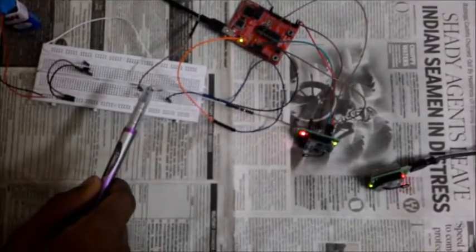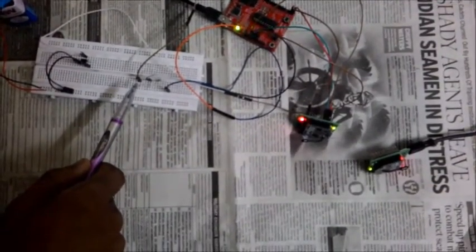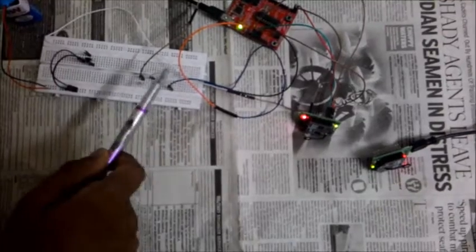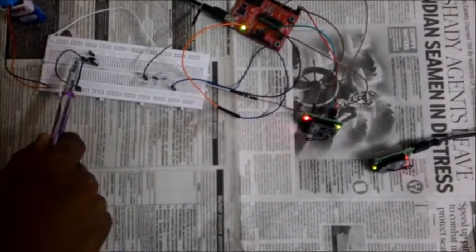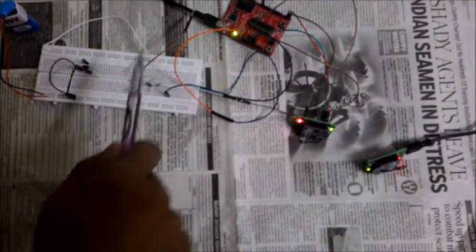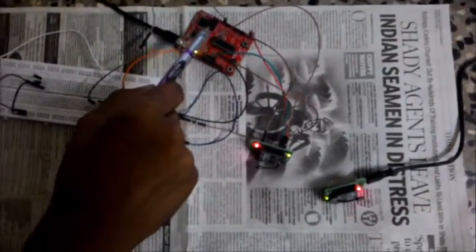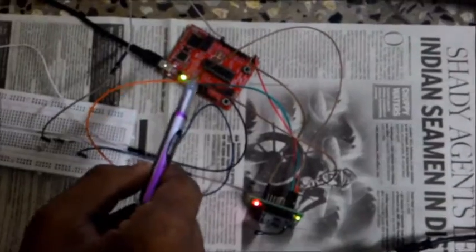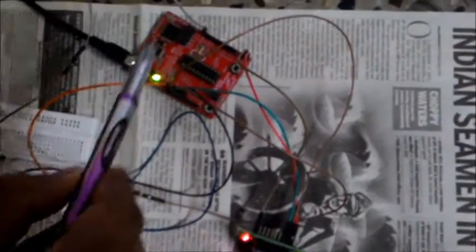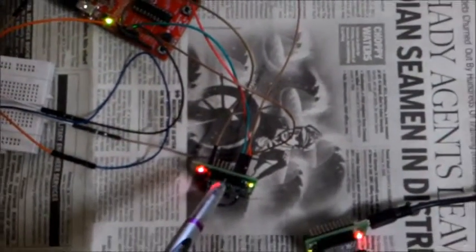Guys, now I will explain the hardware part. This is an LDR sensor, a light dependent resistor, which we use to measure the intensity of light in the room. This is the LM35 sensor, which measures the temperature in the room, and the two sensors continuously send analog data to the MSP430 microcontroller. The MSP430 compares these values and converts them to digital through a 10-bit ADC, and transmits them through this router Zigbee to the coordinator Zigbee, which is connected to another port.